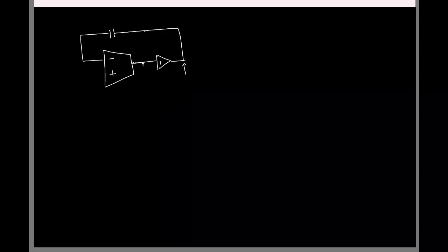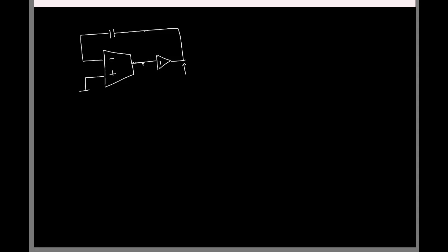So, yeah, this is a nice way. But again, as I mentioned, in practice this buffer cannot provide a gain of 1. Say it gives a gain of 0.7 or something. So let's say you design this to have a gain of 100. At this point, you might have a gain of 100, but at this point, you kind of lose something. So what do you suggest we do?